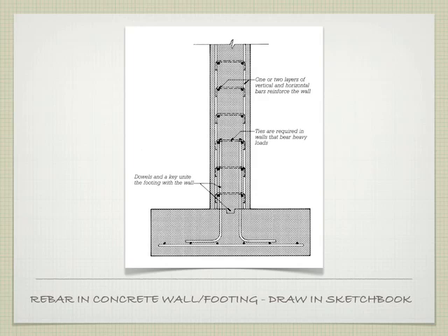So this is going to be the next slide, but I'm glad you asked, right? If we needed to splice two pieces of rebar together, we know from the last class that they have to overlap by a certain amount. Anybody remember? 30 times the diameter of the rebar, right? So this overlap here needs to be 30 times the diameter of the rebar. Okay? Make sense? Okay, good.